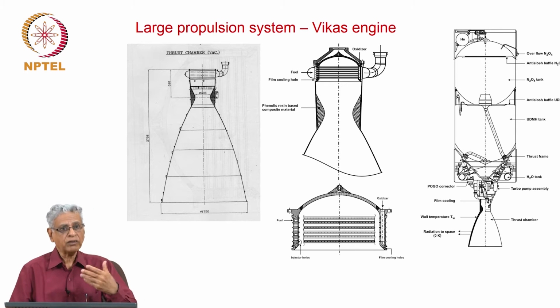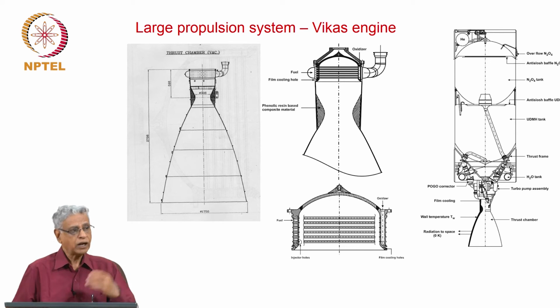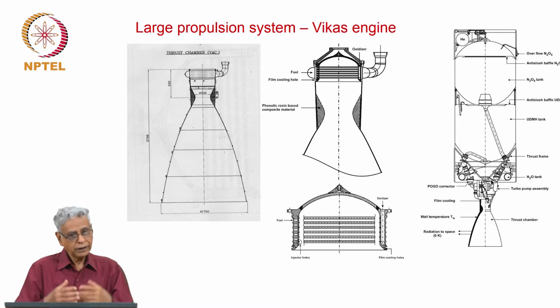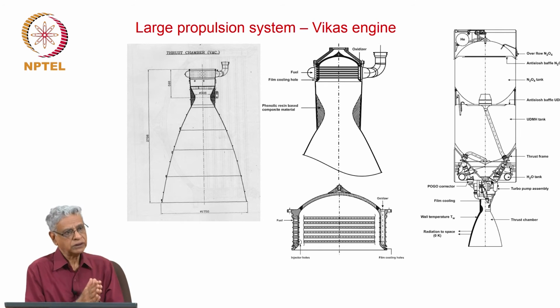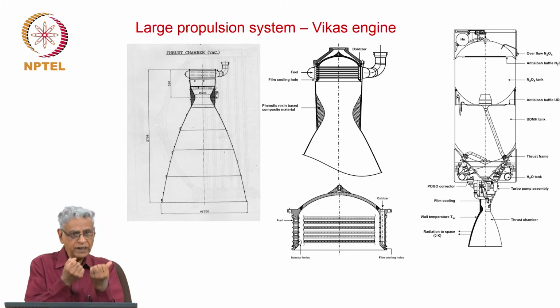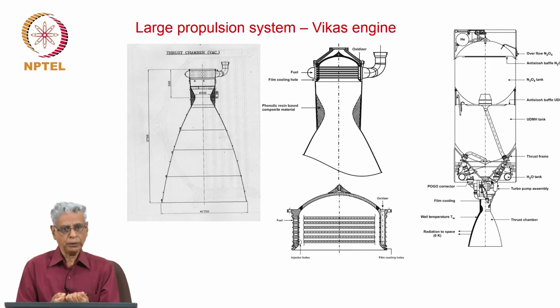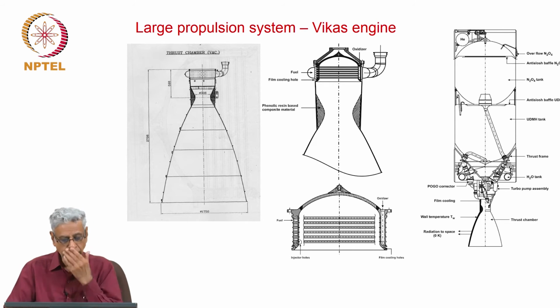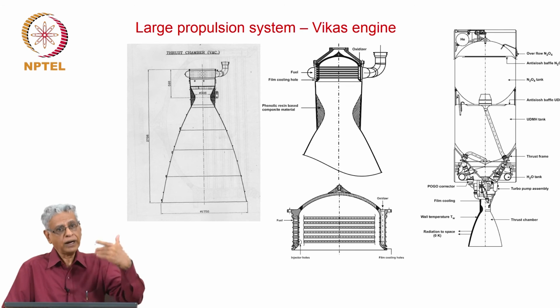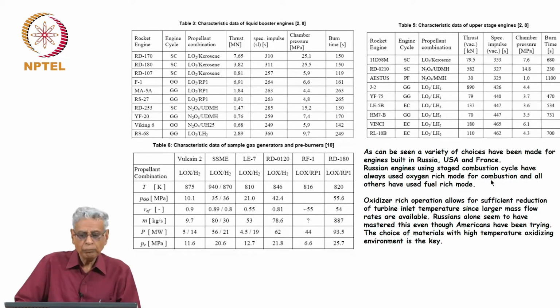In the early part of development, the Saturn vehicle had some difficulties, and they applied their mind to how to overcome that. From that point onward, the pogo corrector is one of the elements of design. It's a combination of structures and propulsion, a feed system coupled to the thrust chamber. The specific analysis tools which are used to understand pogo and remove it, I have put together here.